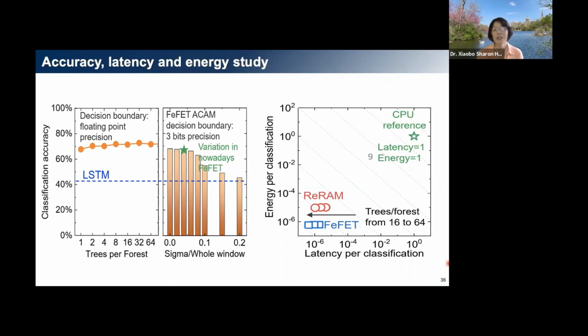And very recently, we just submitted an IEDM paper looking at another type of FeFETs that we call back end of line FeFETs. They are using a different way. Instead of integrating the FeFETs into the gate stack of a traditional CMOS, they are building the FeFET device using the back end of line. They are a different type of FeFETs, and that allows us a better way to integrate, because that opens up 3D integration opportunities. So again, definitely a very, very exciting area. If you haven't looked into that, and this is a direction you're interested in, definitely look into it.